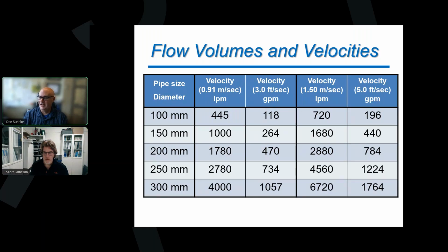Bruno asks, how do you check the biofilm reduction? The test would only show the planktonic bacteria. Bruno, you're going to want to do what's called a heterotrophic plate count in those cases. It's sampled and tested the same way that you're normally doing your coliform testing.